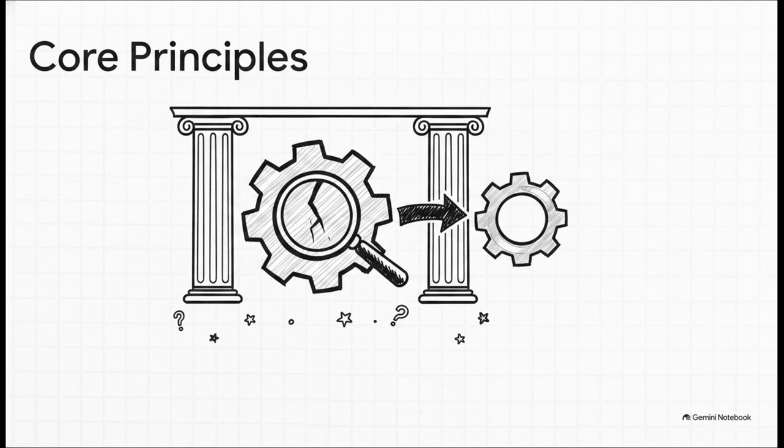And I love this part. In this framework, failure is a highly successful data-gathering step. A failed iteration is incredibly useful if it isolates a specific mechanism, like, say, a pole dominating your phase margin, and then yields a corrective direction. It's all about taking narrow, testable steps that look a lot more like controlled experiments.